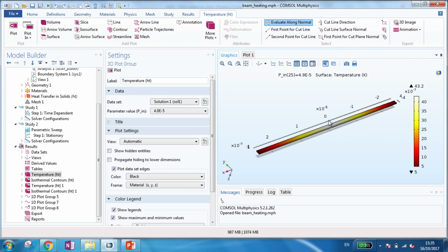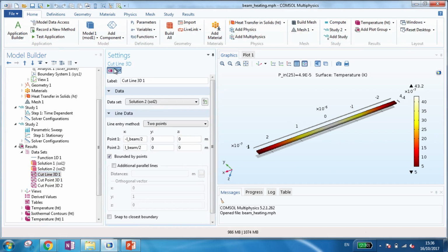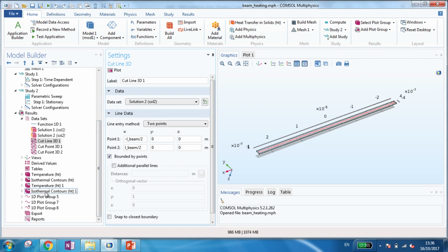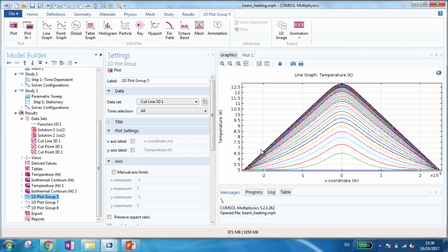And if you think about it, it's not that crazy. I mean, what is the diffusion equation in 1D? If you imagine your beam is 1D, at stationary the second derivative of your temperature is a constant, so it gives you just a slope. I'm sorry, the second derivative is 0. And then it gives you just two linear functions with a maximum at the center. So it's not that crazy.